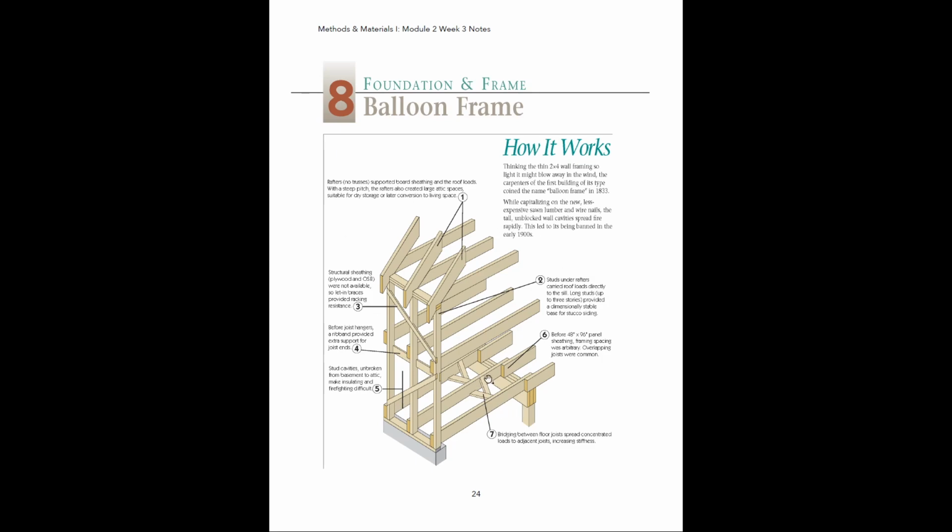Okay, but in a lot of older houses, you're going to come into contact with this. You can see here, if you look at these joists that are running, so these are the joists that your first floor is going to sit on. The joists are split, okay, and they kind of butt up to each other. And then where they are split, there is this large beam down in the basement that is going to be carrying the load of those, okay? So they are sitting right on top of that beam, and that beam is going to run from one end of the house to the other. It's going to support all this weight here.